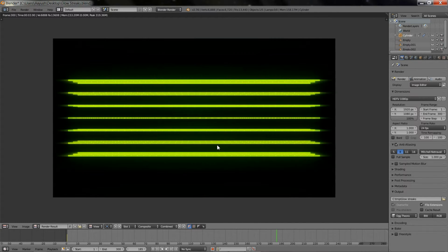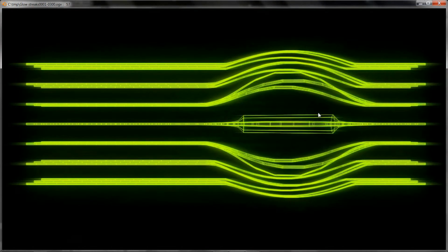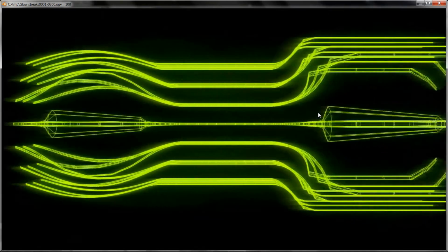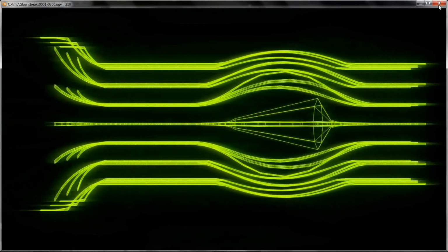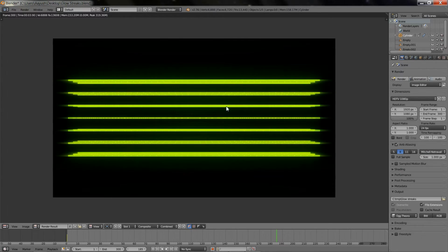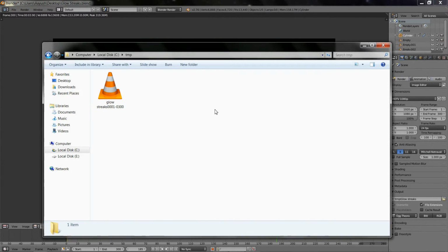Our animation has now finished rendering. It took my PC around 20 minutes to render these 300 frames. You can now view the animation. For that, go to Render menu and choose Play Rendered Animation. You can also browse the file in the Explorer and use any third-party player to play the video file.